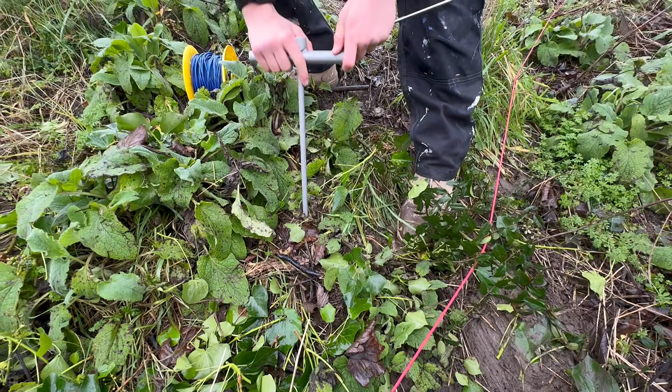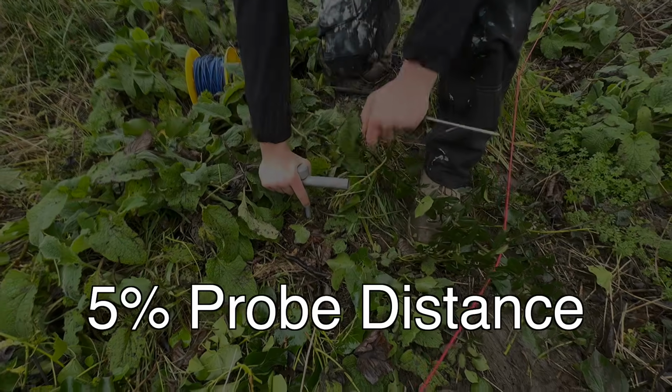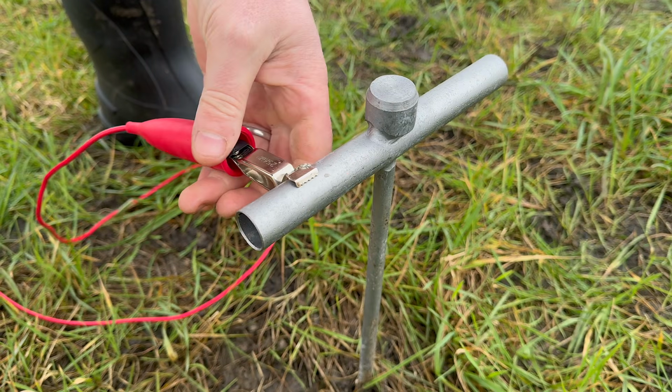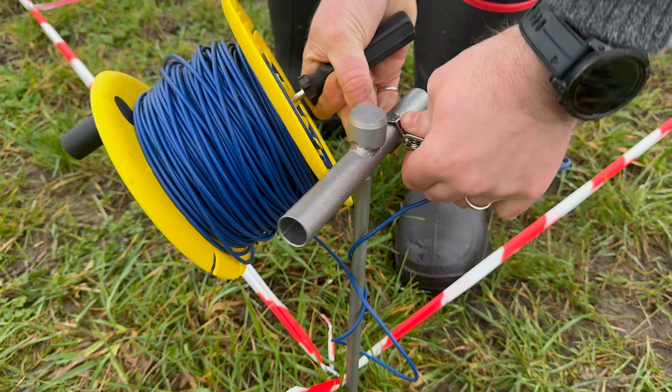And an important consideration here is the depth in which we bury the probes, because that really does matter. As a rule of thumb, the depth of each probe should be no more than about 5% of the distance between the probes. With a 1 metre spacing, that means the probes are typically driven around 50 millimetres into the ground. This keeps the measurement focused on the soil volume between the probes rather than deeper layers of the soil which would distort the results.